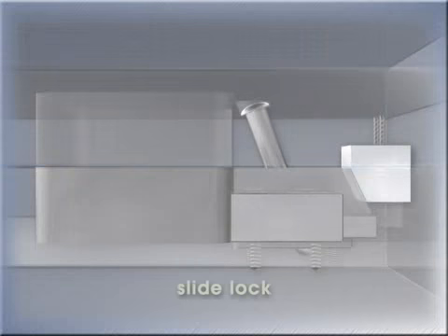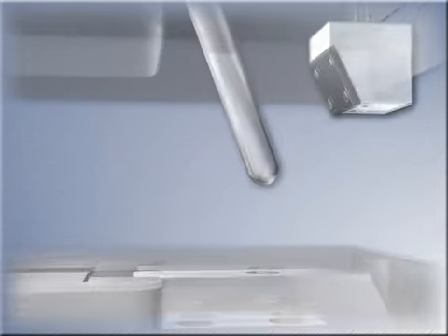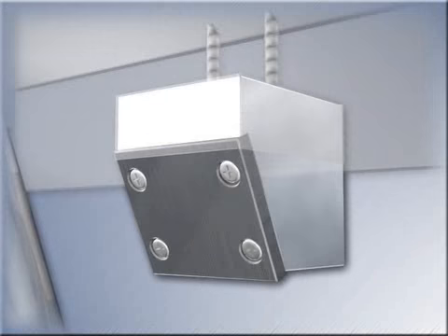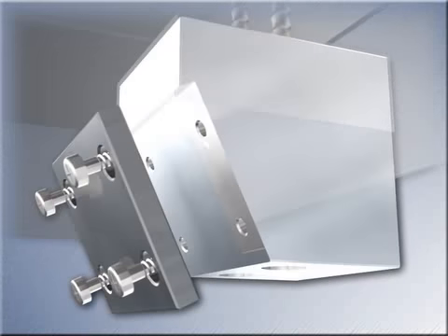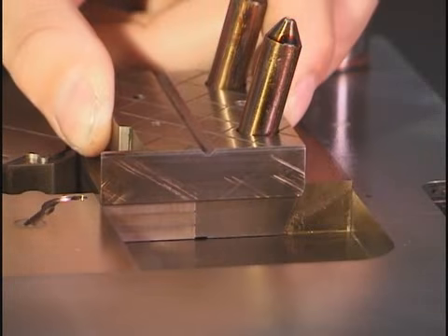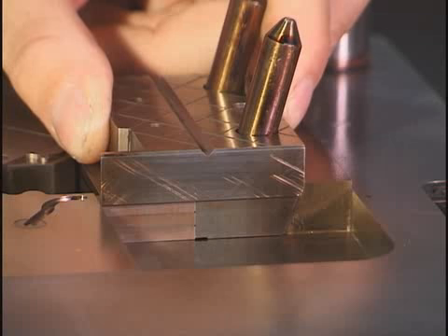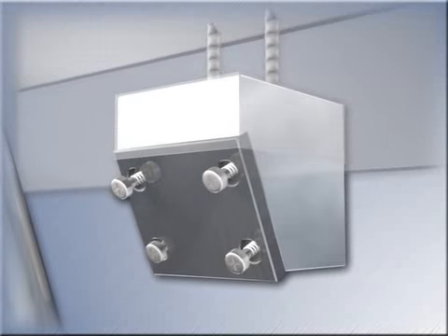A slide lock holds the slide in place during injection. A heel block applies pressure to the slide block when the mold is clamped. Due to the forces applied to the heel block, a small wear plate can be used to ease replacement when wear is evident. The angle ground onto the back of the slide block corresponds with the angle on the face of the heel block. This angle is typically 10 to 20 degrees and locks after the slide has been put in place by the actuator.